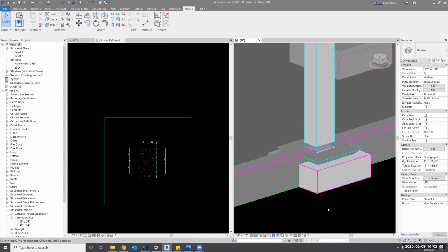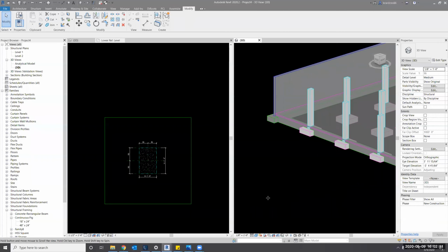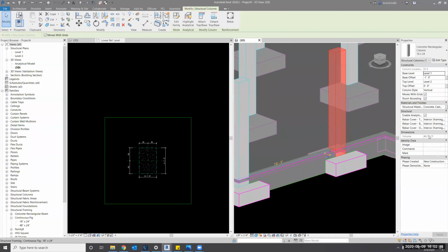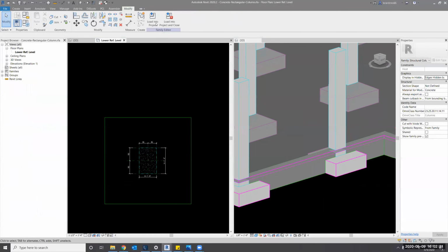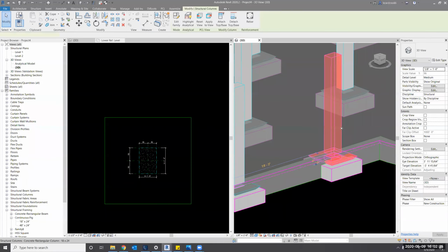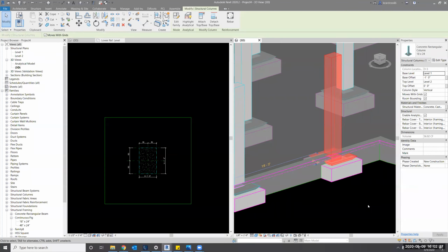Because let's do a quick undo on your keyboard, hit Control Z. If you select one of these columns, you already had a volume set. If we load the family back in, load in a project, yes, overwrite. It was 46 before, now I've got 56. So that's reporting incorrect information.